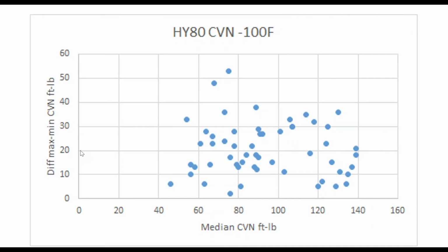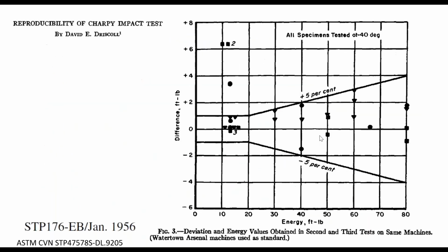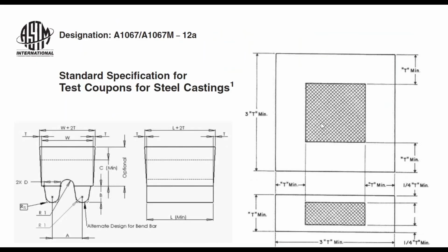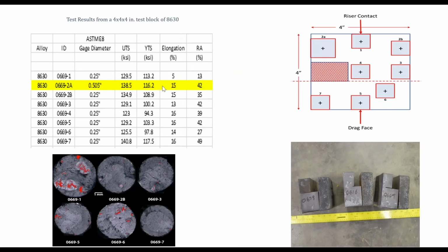Part of that is how small a specimen you're really looking at. For a 505 tensile test with a 2-inch gauge length, you're only looking at a 3/4 inch cube of steel that you're measuring, which is really small. One of the things I forgot to point out up here is that the large specimen typically gives you better properties than the small specimen.